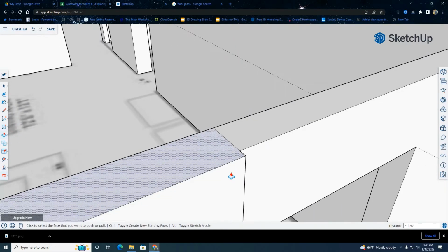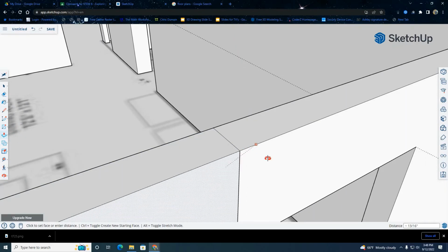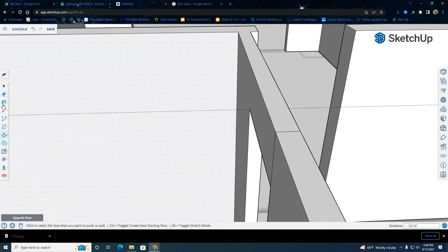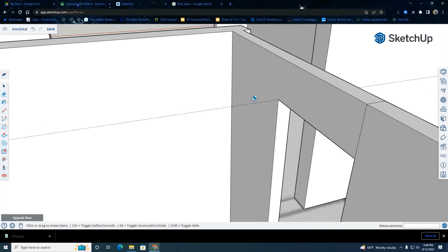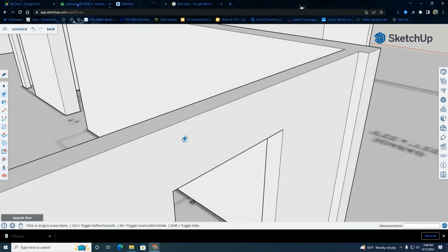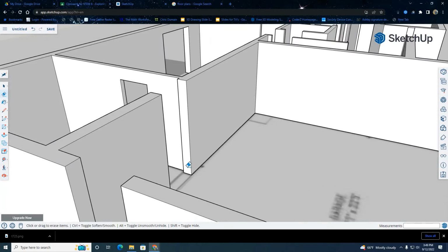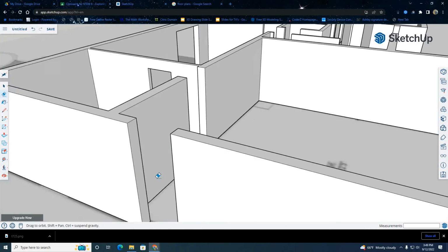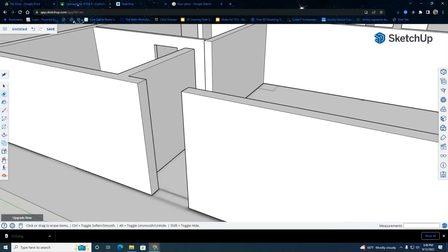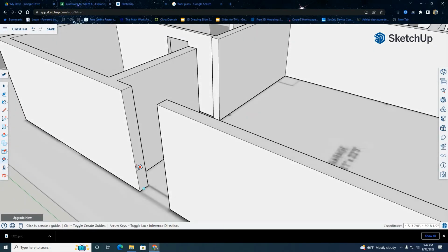So I'm gonna just bring these two thicker walls. I usually try to get the thicker wall to come in, and then erase. If everything is done right, it should be fine. There you go. I'll show you one example of something that might be useful. Taking the tape measure tool, going up 7 feet, enter, taking the pencil tool, and just bringing that over.